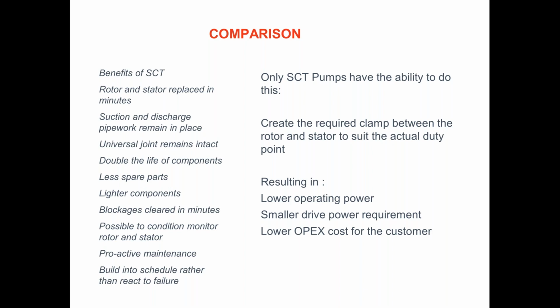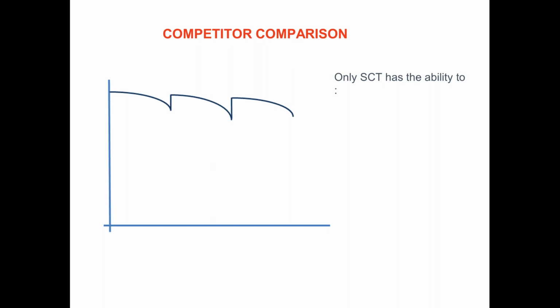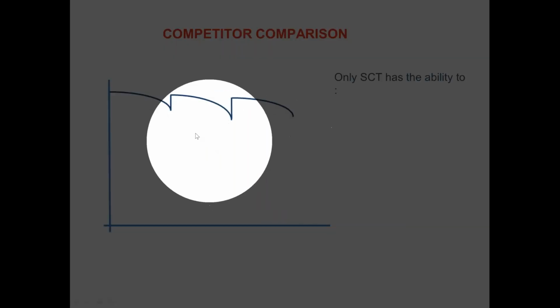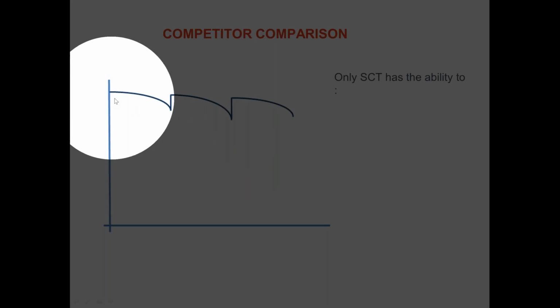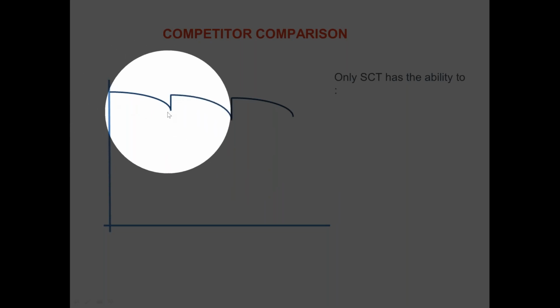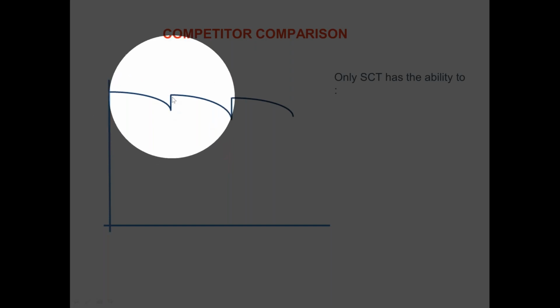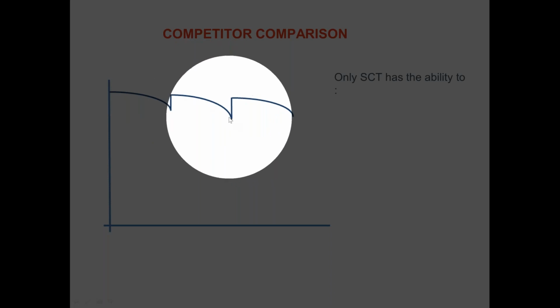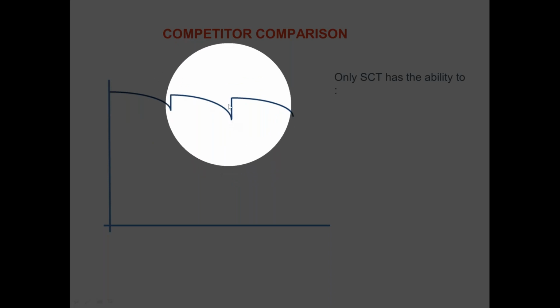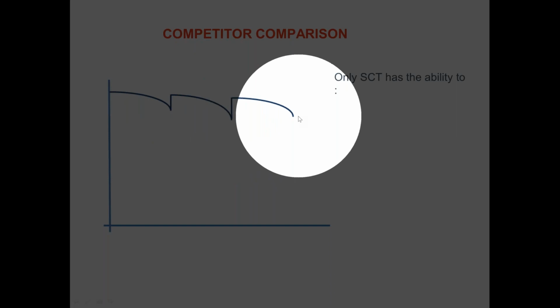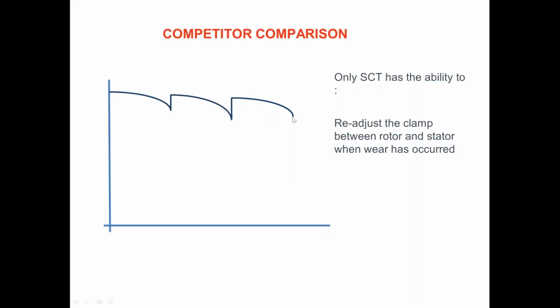Proactive maintenance. Because the pump is starting to reduce its flow per RPM, rather than speeding up the pump, the operator can recompress the rotor and stator. Recompressing would happen over time. Let's say after 3 years, the pump started to reduce its flow per RPM. The operator could tighten this pump back up, get it back to its original flow conditions, let that wear again over, let's say, a year's time, tighten it again back to original tolerances, and let that pump wear for perhaps a 3rd time.